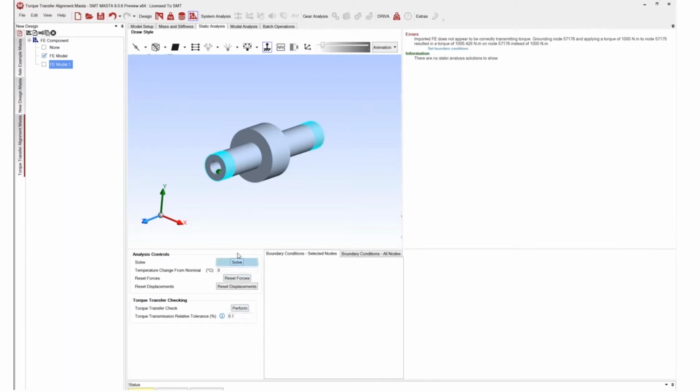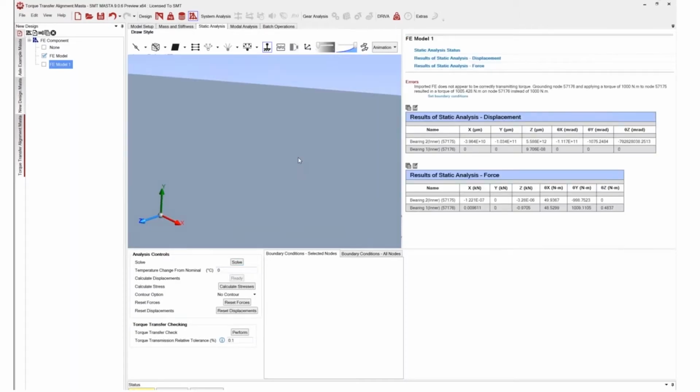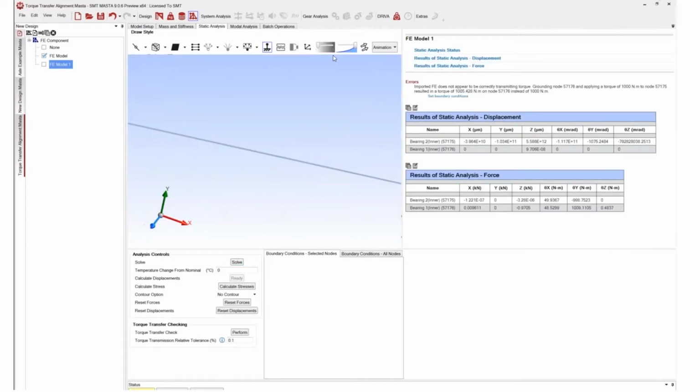We can set those boundary conditions to check ourselves. We can see things have gone quite horribly wrong. It's all flying to pieces. We've got some ginormous displacements here because we've got that zero stiffness in there, and it's a very badly defined problem now.